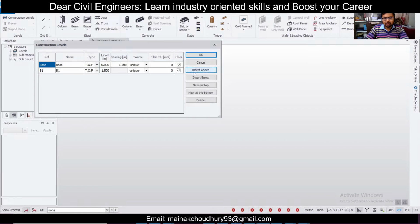I'm going to go a level above, and the spacing which I'm going to give here is 3.2 meters. This particular floor will be my ground floor slab, my first slab. So this will be SSL, or structural slab level. TOF means top of foundation or top of footing, and TOS is used for steel structures, top of steel. So I'm going to use SSL here, structural slab level, 3.2 meters.